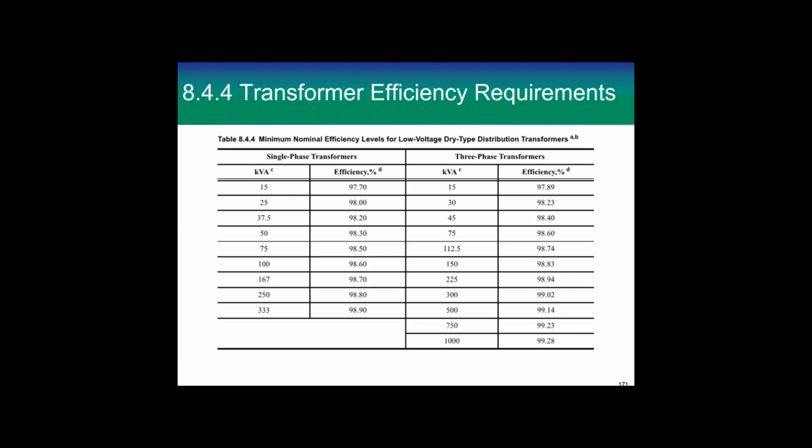Transformer efficiency requirements are listed in 8.4.4. Now, these are actually set by the federal government, but again, we wanted to show them to you. And so these are good for the electrical engineers, but they're also good for us. If you're looking at how efficient they are, and so how much heat they might be giving off, you can look here and you can get a good idea of the amount of heat that would come off of a transformer in the electrical.